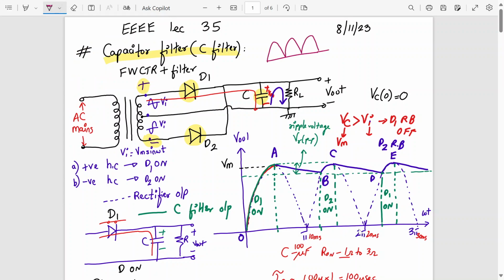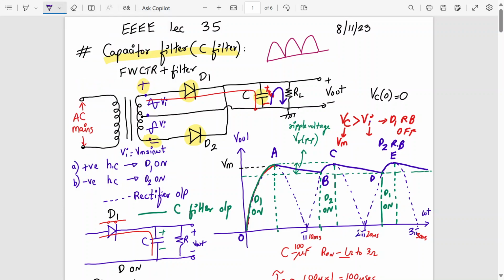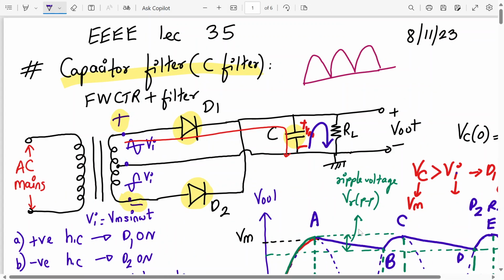And you have understood. Now, this contains a high value of ripple. Somehow we are connecting the capacitor. I hope you're following this. Now what happens with the capacitor? The capacitor charges instantly, very fast, and it discharges very slowly. So your waveform will be like this here. I think you have verified this in one of the experiments also. So your waveform gets converted to this. This is the filtered output and this is the rectified output. So that is what we want.